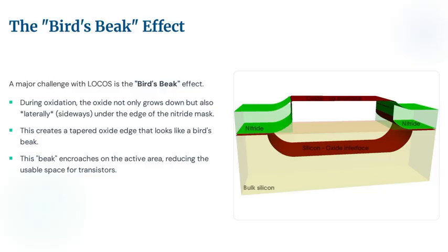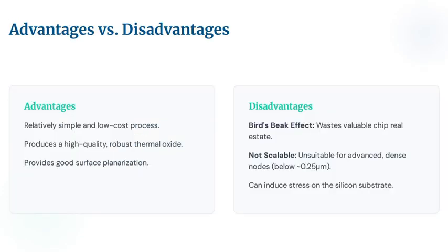This means that after the completion of this oxidation, we have to remove the silicon nitride, and that site should be filled with gate oxide. When we have another oxide under that with a different shape, the shape of the gate oxide that needs to be fabricated on the non-isolation regions will also change, and we have various specifications for gate oxide widths and lengths. If that width and length are altered, there will be formation of parasitic capacitance and unnecessary effects on the working of transistors. So that is the main problem of this low cost process. As I told earlier, the main disadvantage of the low cost process is the bird's beak effect.